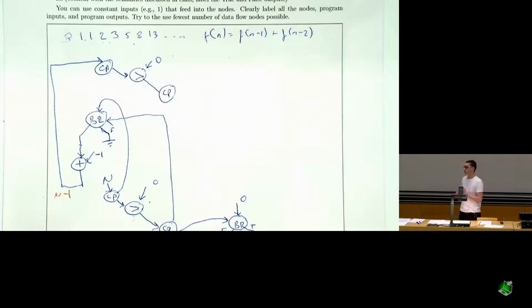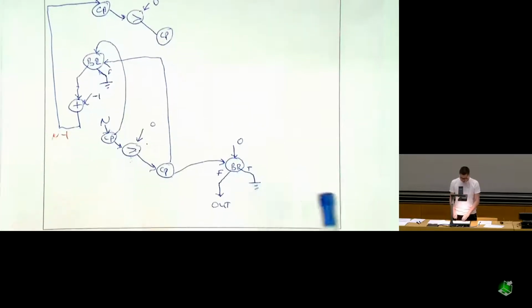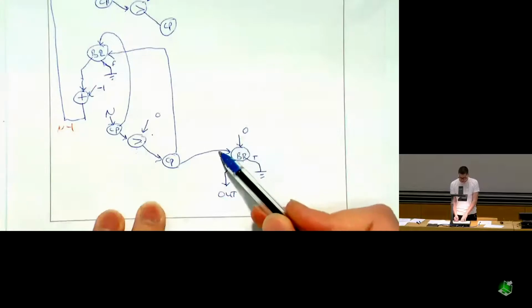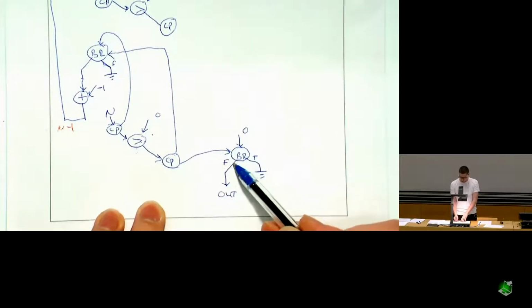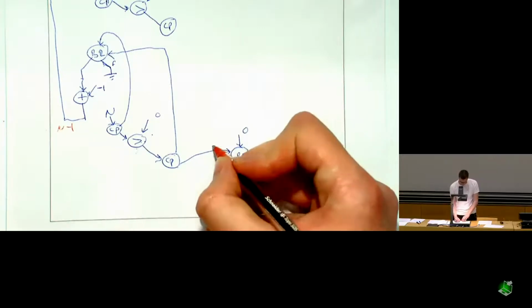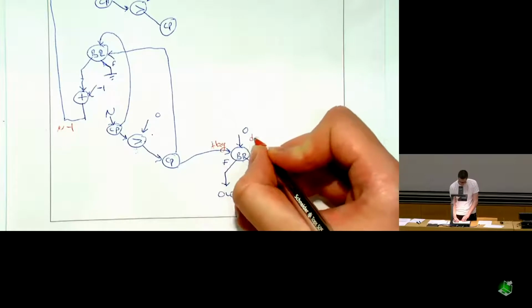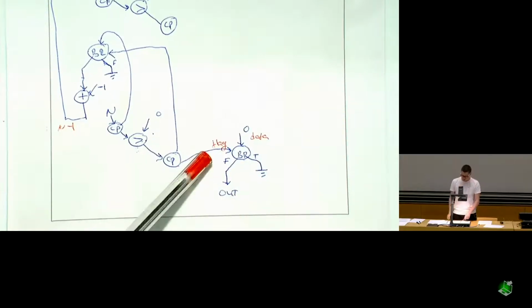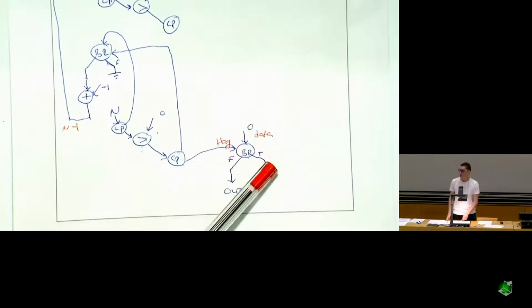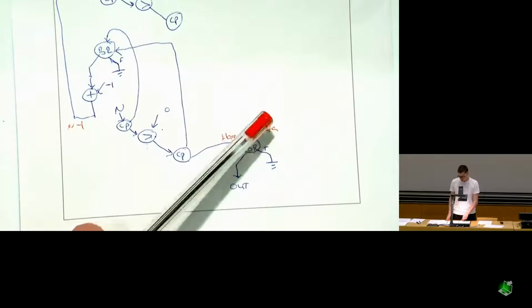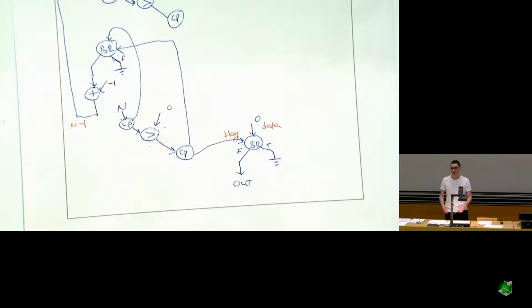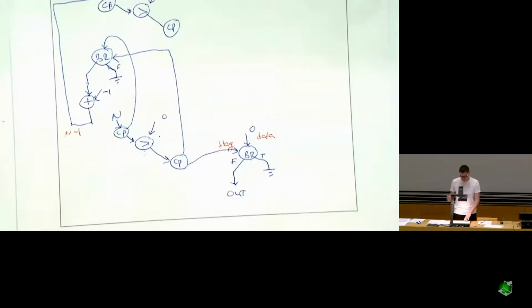Can you quickly recall how the branch node works? Yeah, sure. So the branch has 2 inputs, right? Both inputs should be valid, and it outputs either from the false path or the true path. One of the inputs is the flag, and one of the inputs is data. If the flag is true, the data goes to the true path. If the flag is false, data goes to the false path. So the token is generated only on one of the output paths in the branch node. Is it clear? Okay.